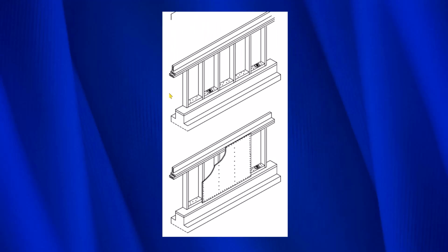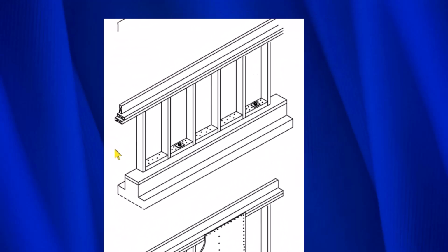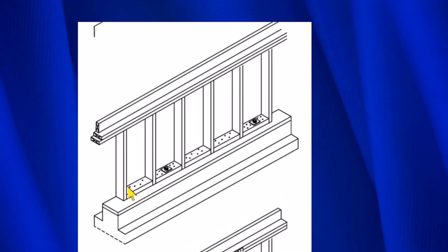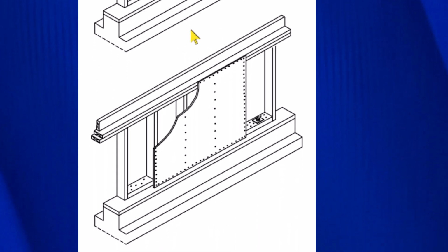Here's another method by which the plywood is attached to the bolts, and that's with blocks. So you see a block right here between the 2x4s, another block here between the 2x4s, here and here, and then these bolts go straight through the blocks into the concrete, and you'll see another one right here that goes straight through the blocks into the concrete. And when that's all done, we take the piece of plywood and nail it straight into the blocks that you would see behind here. Now remember, these blocks are made out of very low quality wood.